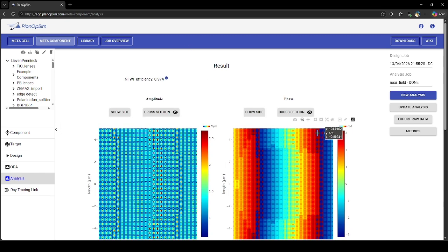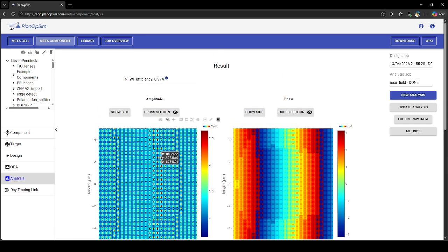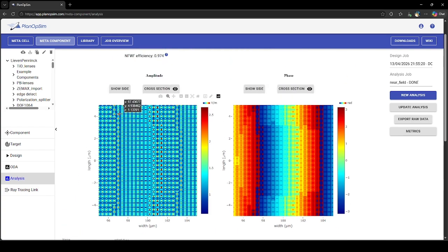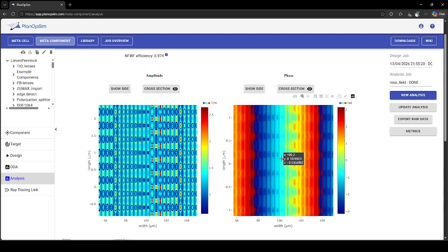Voila, and this calculation has now run, and we see the near field wavefront profile, the wavefront right after the metasurface associated with this metasurface. And if we zoom in a little bit here, we can actually see the signature in the near field of each of these nanostructures that we have. So nominally, each of these pillars produces a certain phase, but if we then look in detail, we see that they also have their own amplitude and phase profile locally within the unit cell, and we can analyze this in detail